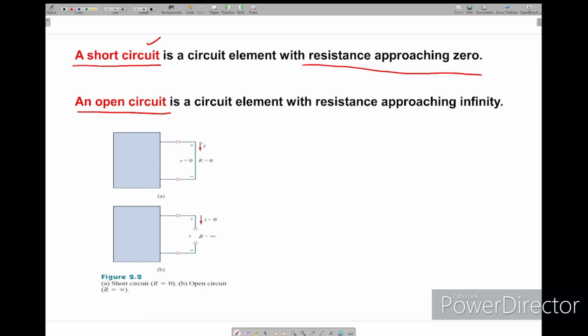If you see this is one network. Here resistance is 0. If you want to make a short circuit of that network at a particular node, it will be like this, because these two nodes are joined together. This is the short circuit path. Here, as per Ohm's law, we have V equals IR. So if you want to know I in the short circuit path, I equals V by R.